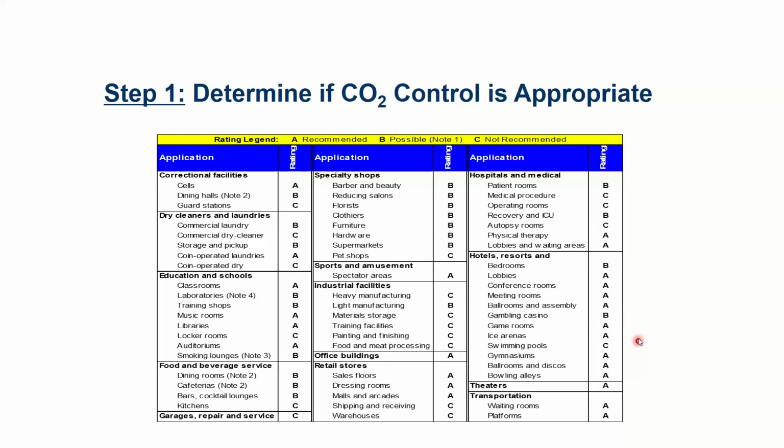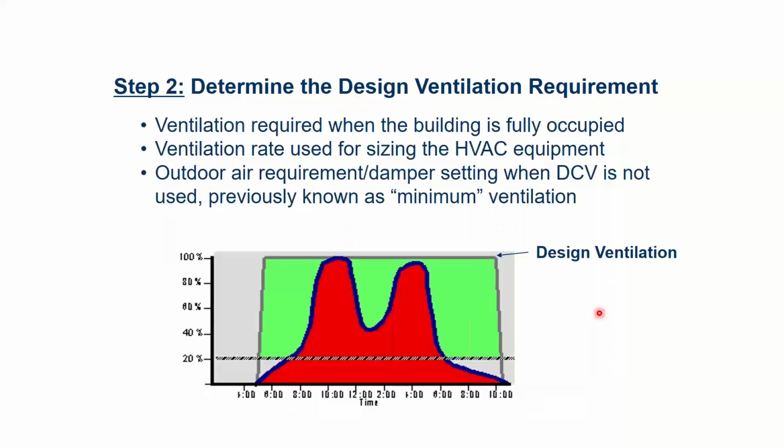And then the maybes, we just got to ask questions on. Like any of these ones here, they might have weird chemicals going on, right? Like a nail salon. So I got to think about those and how you're ventilating it. And I might say yes, I might say no, depending on what you're doing there, right? For example, the nail salon thing. Some of the higher end nail salons have an exhaust fan right at the technician station. So they're exhausting directly off of your hands. In those cases, I could mess around with the ventilation rate in the main space. But in a lot of places, they don't have that exhaust fan. They have a general exhaust for the whole room. In that case, I'm not messing around with the makeup air coming in, right? So those are some things to think about when we're controlling these things.